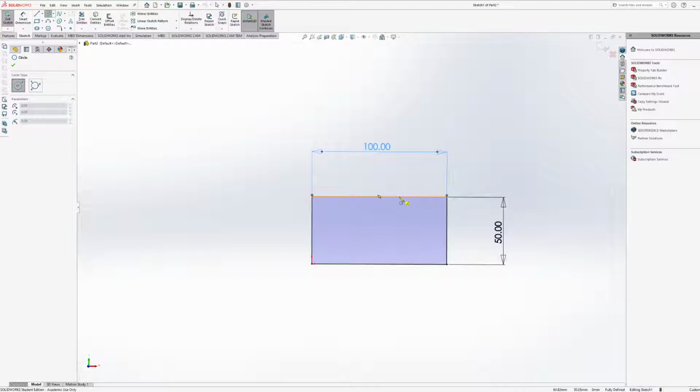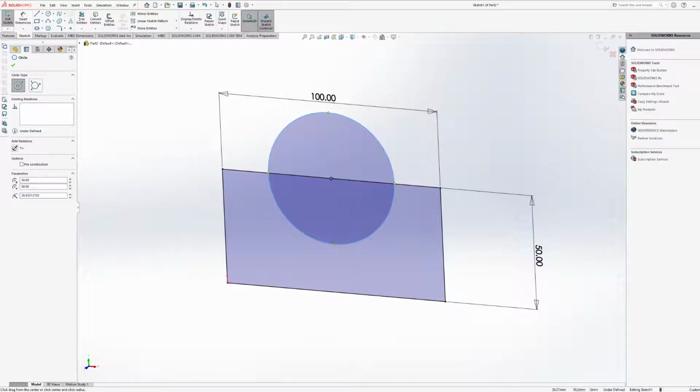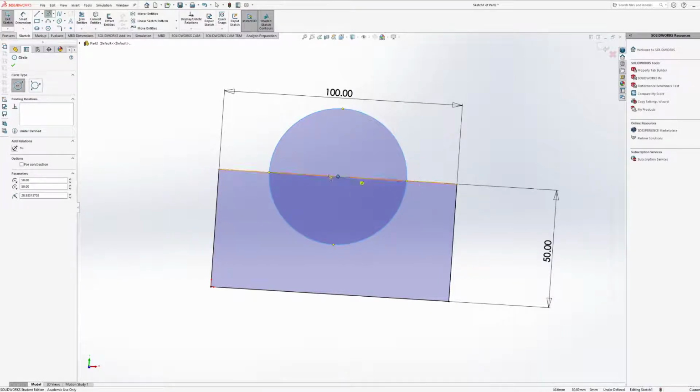One thing that you just need to be careful about is that sometimes you might place another sketch, be it a cylinder, in a specific place. Usually whenever you see these dots, this yellow one here is indicating that it is the midpoint. So if I start there and continue that sketch, it's going to make sure that this circle has a center on the midpoint. So it's already centered on the center of this top line.